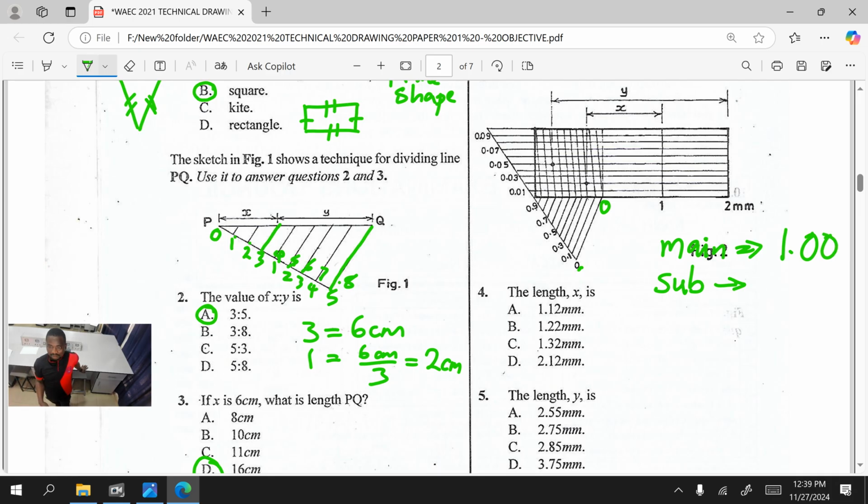So this is the diagonal scale. Then for the subscale, you have to check the horizontal subscale followed by the vertical subscale. So for the horizontal first scale, we need to count. What is it? 1, 2. Can you see that now? So that will be what? 0.2. 1 decimal place. Then for the vertical scale, is going to be 2 decimal place. So let's count. 1, 2. Can you see that now? So that is also 0.02. Do you get it now?